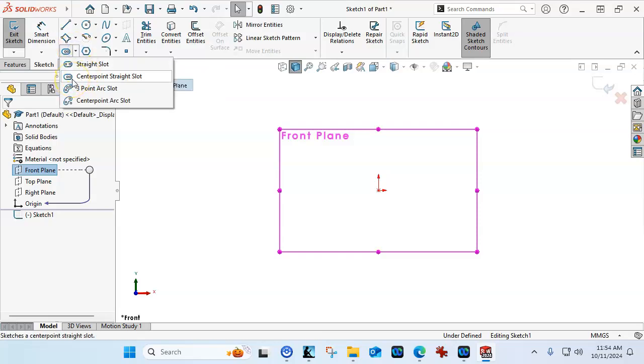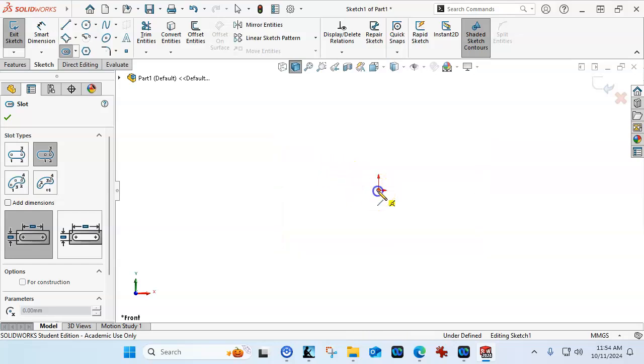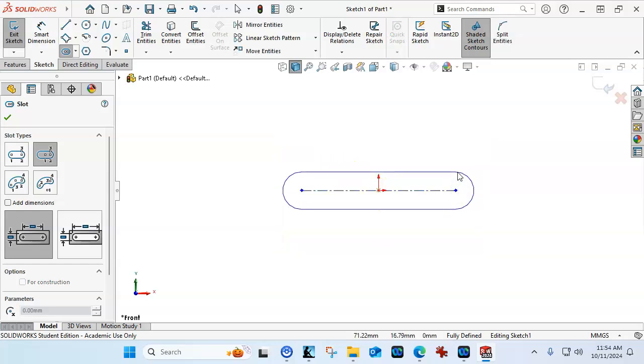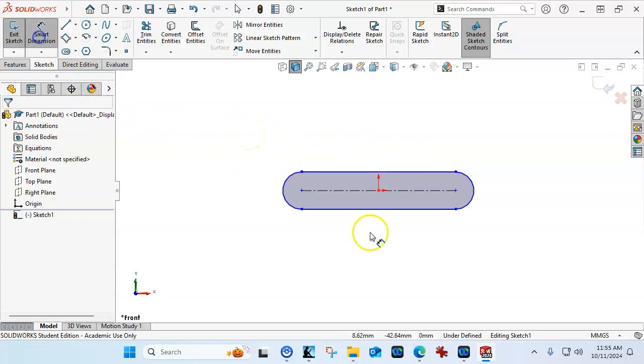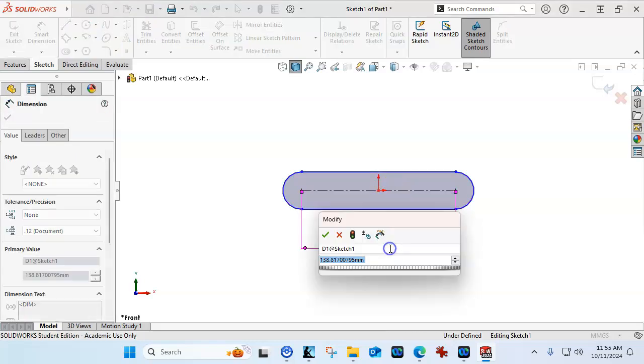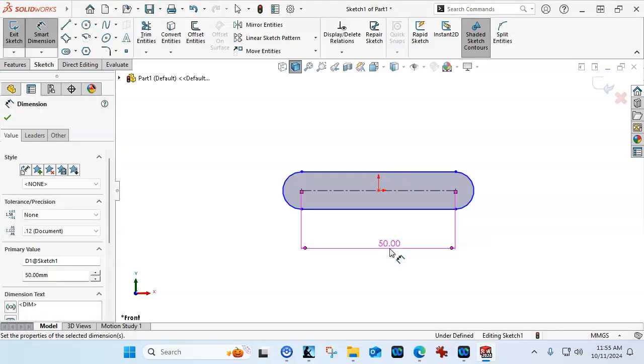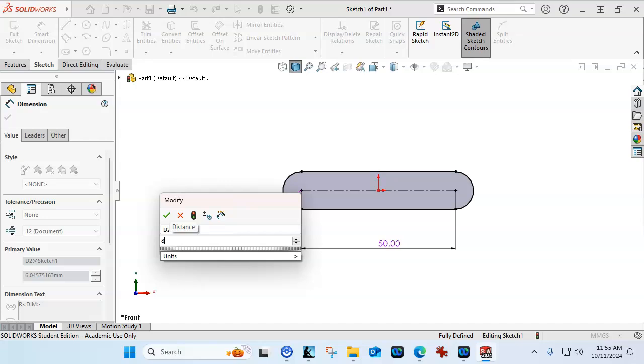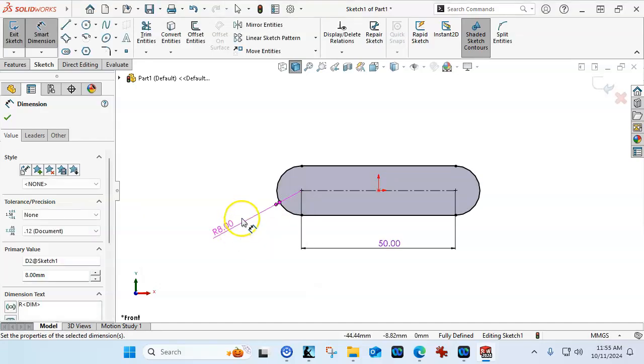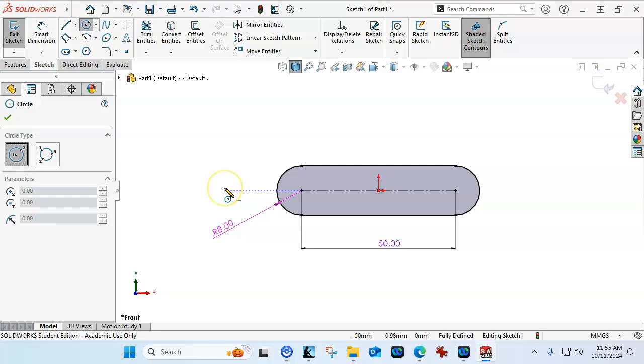I've been paying attention to the dimensioning, that when I'm building these odd-round shapes with the slot tool, the drawings are acting a little on the maybe unpredictable side, or not the way that I expect. All right, so I can dimension the center line for 50. They're showing 10 on either side. Radius of 8. And we have the two holes.